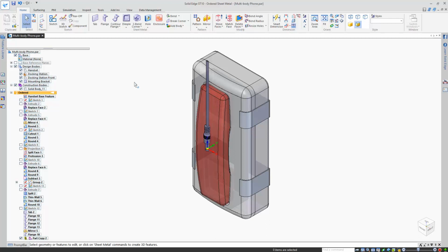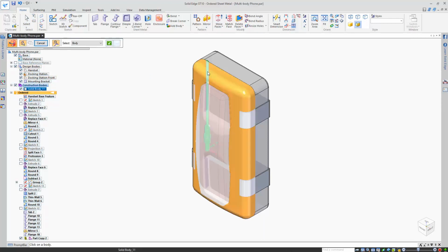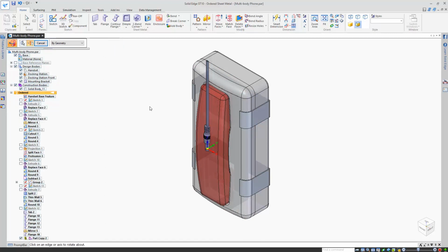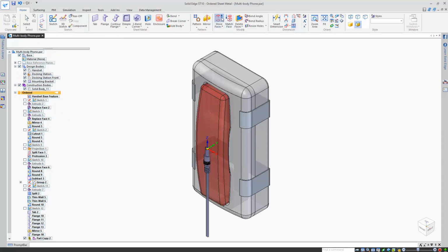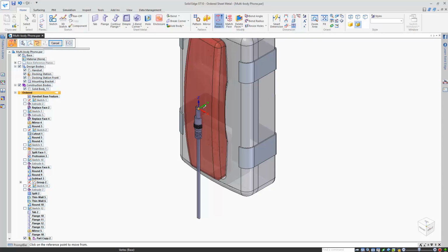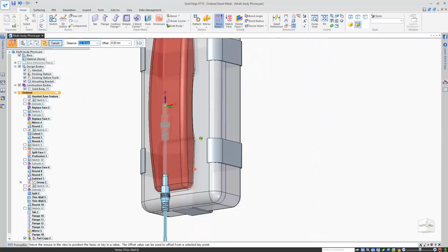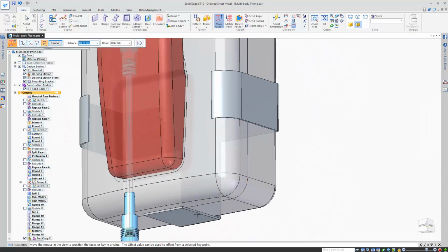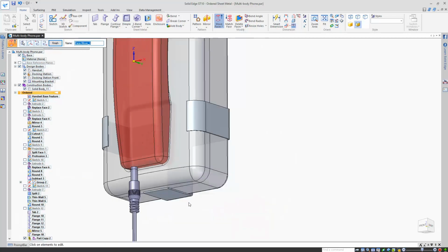Now you'll notice that this component's been brought in with an incorrect orientation, so I'll need to use the move face commands to move it into position. This would be easier in synchronous, but in ordered mode we have history-based links between bodies, so that's the environment I'll be using for now. I'll rotate this DC cable about the x-axis by 180 degrees, and then down by using 2 key points. And now into the middle of the back of the docking station.